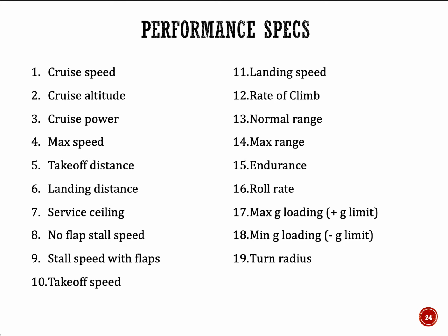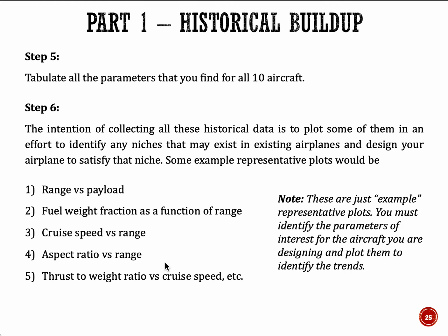And if you're doing some aerobatic aircraft, the max and min G loading is also important, correct? So make sure to identify what is very important to you, and you have to collect that. But cruise speed, cruise altitude, landing distance, no matter what, you need those for all types of aircraft, right? So the goal here is to, again, collect a good chunk of these data, so that you'll make a very informed decision when we're going to set the requirements.